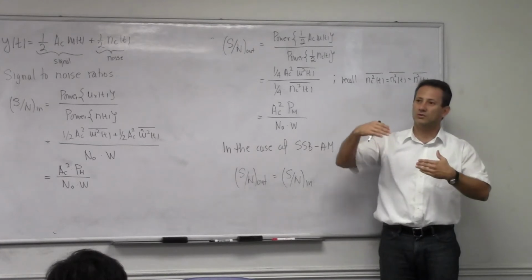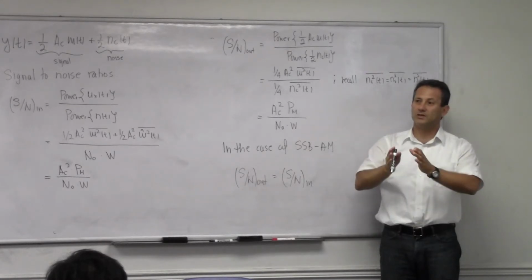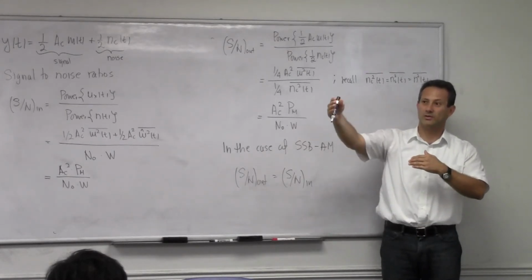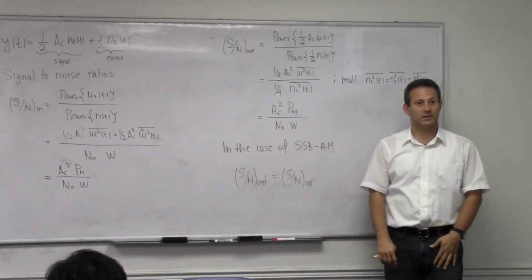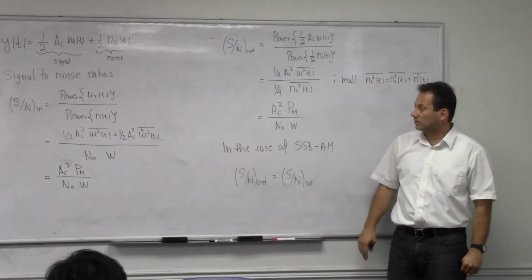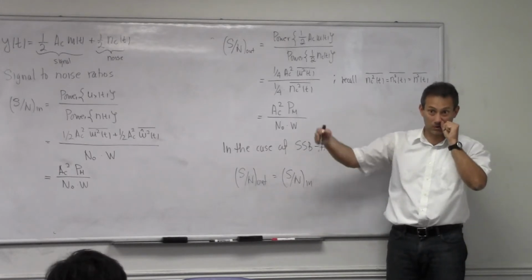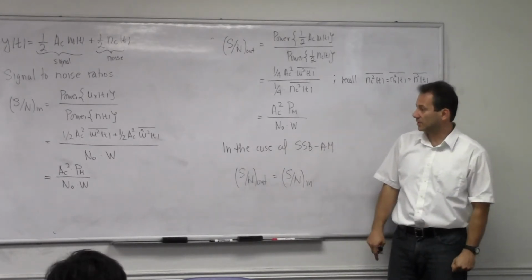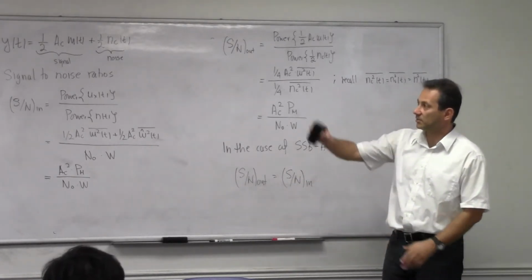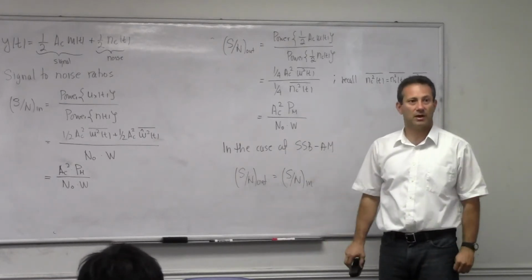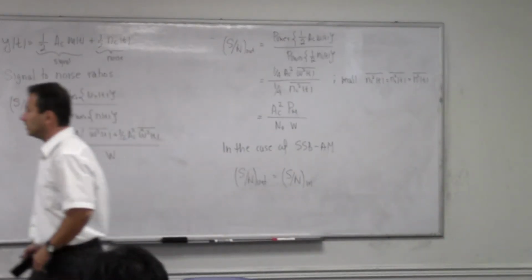Let's say you want to go large distances, right? You can actually use a narrowband signal, but then you need a lot of power to reach the largest distance. Or you can use a wideband signal, but then your power goes down, the power spectral density goes down. So we're going to look at that in much more detail, especially when it comes to FM and later on in your studies when it comes to digital communication. But at this point, we have finished all the analog modulation schemes. Let me provide you a summary in one spot so that you have all of these input-output relationships, and then we'll do a couple of examples of application of this.